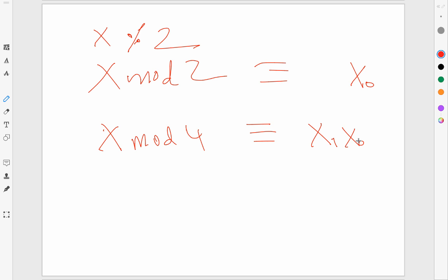Now, having said that, I often have also said that once something is don't care, is there an intelligent way you can pick out of the choices, and that is where other considerations may come into play. But in this example, and generally speaking, it's just fine to put X on the table there. Then, of course, when you implement it, you have to make some choice, whatever leads to the simplest design.